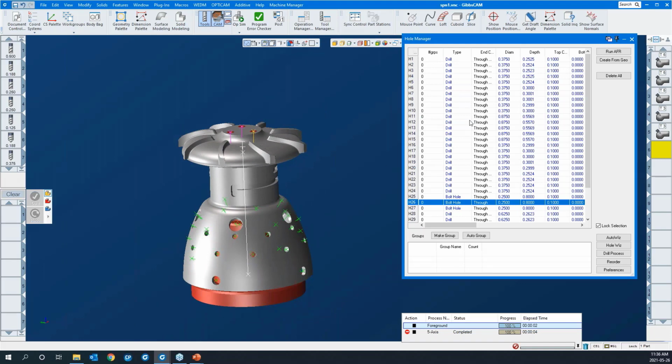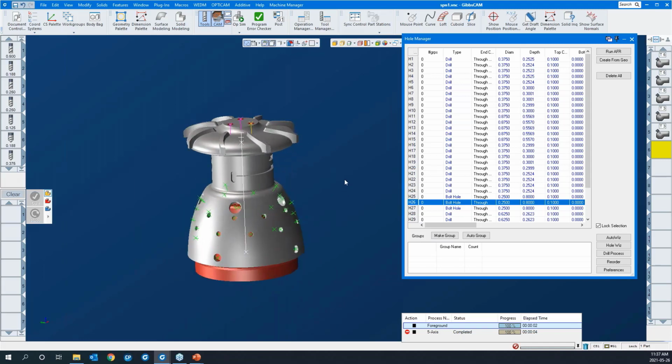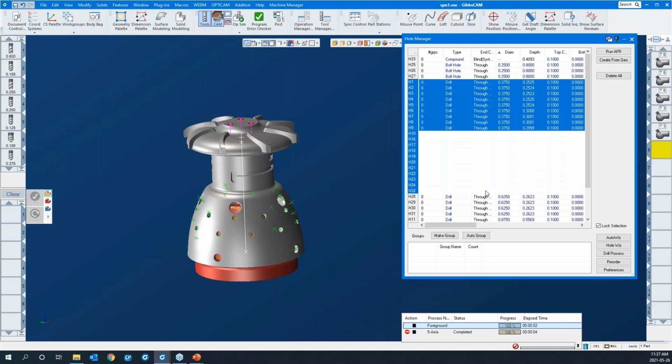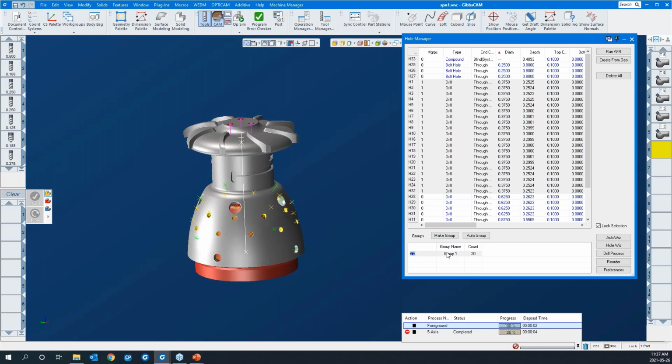There's a series of other ones in here. We can group them together now and then toolpath them all in once, drill them or what have you, all at one time. So I'm going to group them by diameter. I'll grab this 3/8 hole and the rest of them, and I'll say make group. I'll just give it a name, something descriptive.